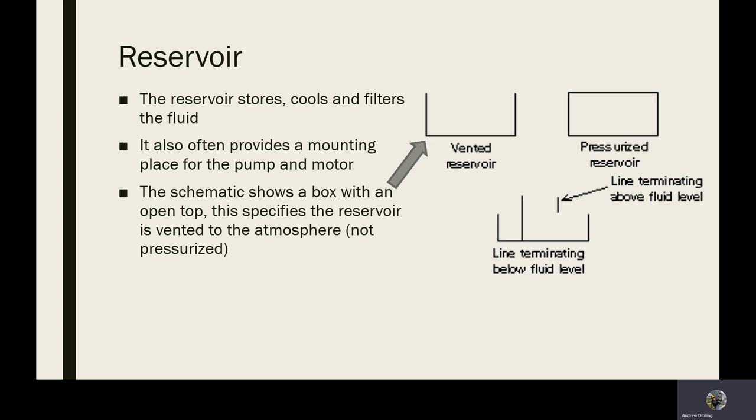A pressurized vessel, a pressurized reservoir is not vented to atmosphere. So it will definitely have a higher pressure in it than a vented reservoir, but the entire system of the hydraulic pack itself may be quite high pressure and should be approached with caution, right?